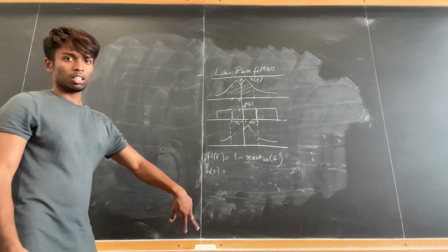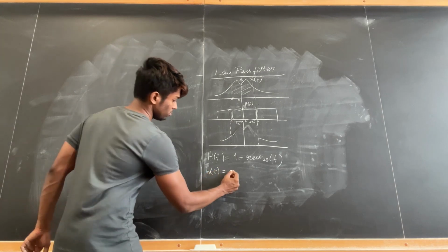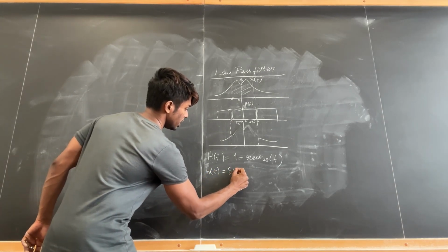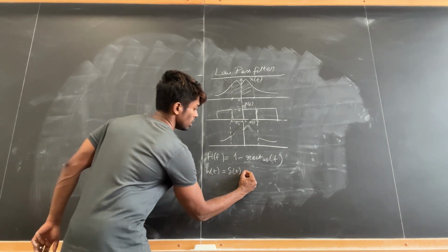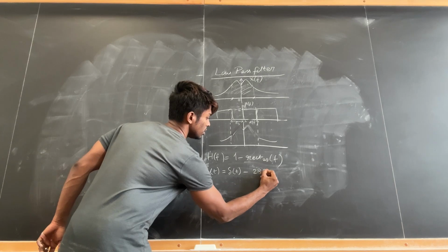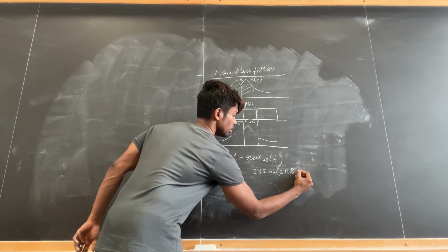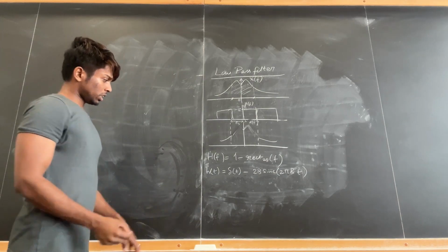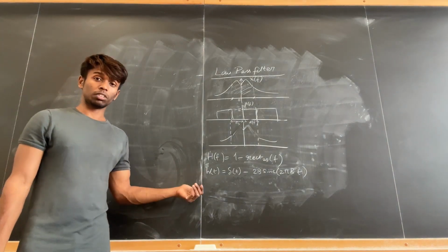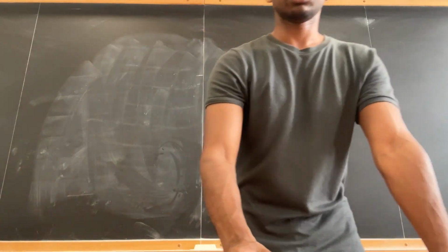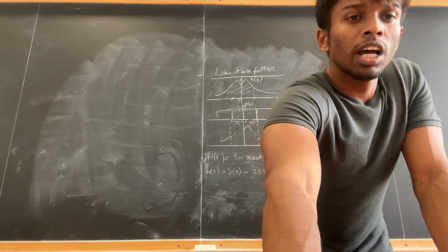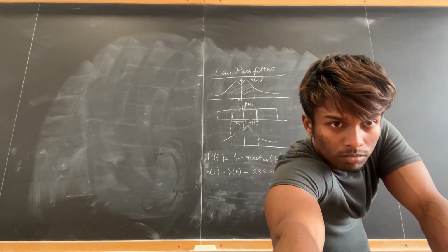Doing an inverse Fourier transform gives us the impulse response h(t). One has an inverse Fourier transform of delta(t) minus 2B sinc(2πBt). So this is the impulse response of the high pass filter, and this is how we can design a low pass filter and a high pass filter.